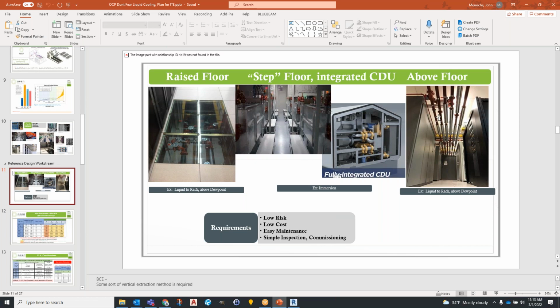Right, and the other part of it is that one of our driving goals is to try to make the facility as modular as possible to accept multiple ACS solutions. And so if we design around, say, a vertical rack, whether it's an RDHX or a cold plate or horizontally loaded immersion, and that's a 2.5 meter tall rack, for example, and somebody comes in after the fact and wants to change out to an immersion tank that needs, say, 2.6 meters total.